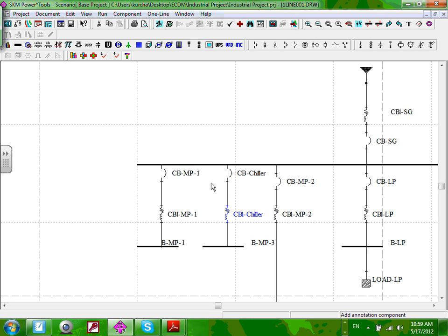So when you do it this way, you have a complete documentation with names for every single feeder. Technically, you can take this information, go tag the feeder with that name, and tie it to the one-line diagram, and it lives forever. That's how they do hospitals, sport arenas, and so forth.